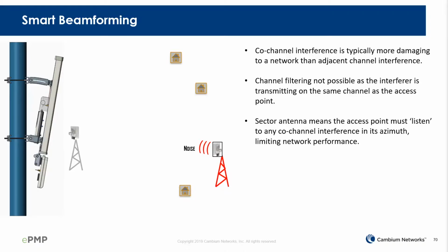In a typical point-to-multipoint deployment, the AP or base station uses a 90-degree beam width sector antenna for data transmission to and from the subscriber modules. The SMs typically have a narrow beam width of around 15 degrees.